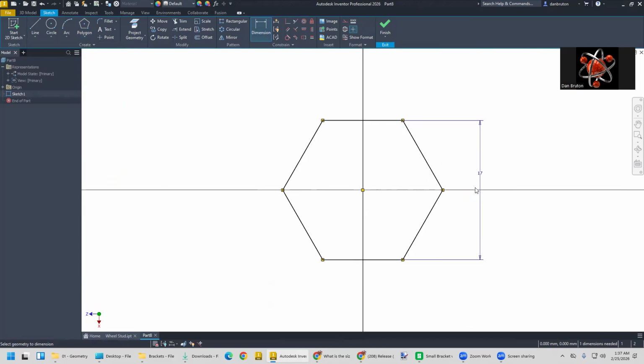17. Usually this is set up so that it accidentally rotates when you grab that. So let's align, is this the right one? Let's align this one with the origin so that you get fully constrained there. Then it's time for the circle. We know it's an M10 bolt, so 10 millimeters, like that.